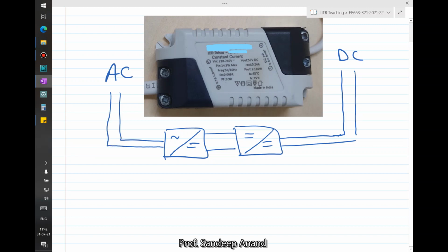So this is roughly the block diagram of this particular one. Now, why did I say it's not that straightforward? Few things to observe. First is this AC power, PAC. If you just multiply the instantaneous AC voltage with the instantaneous values of AC current, what you realize is that this power is not constant. In fact, it is oscillating. It is a function of 2 omega t.